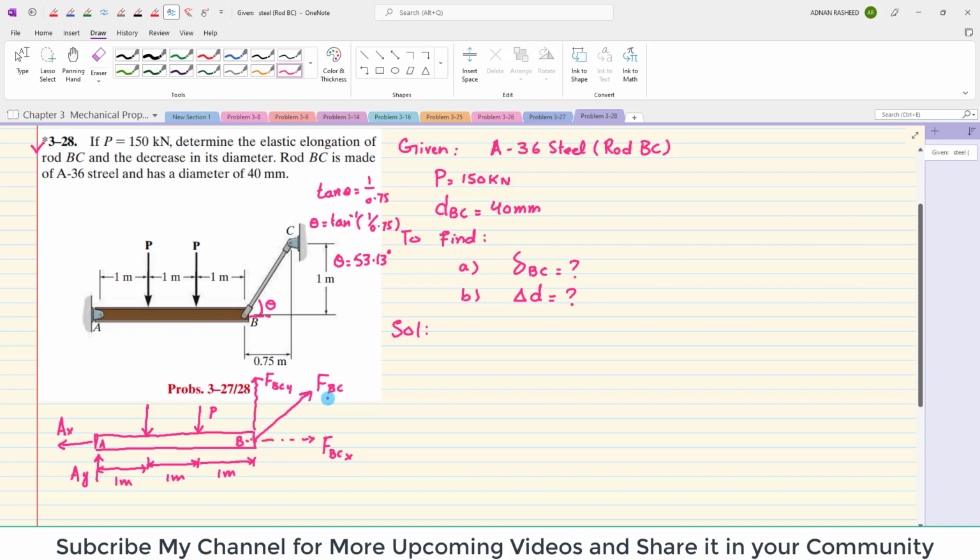Now we are interested in finding F_BC, so we will apply the equilibrium condition that the sum of all moments about point A is equal to 0, taking counterclockwise moment as positive. These two forces pass through point A, so there will be no moment. Due to this force there will be moment. This force is 150 kilonewton times 1, because the perpendicular distance is 1, and it produces clockwise moment, so it is taken as negative. Also this force produces clockwise moment, equal to minus 150 times the perpendicular distance of 2 meter, because 1 meter plus 1 meter is 2 meter.